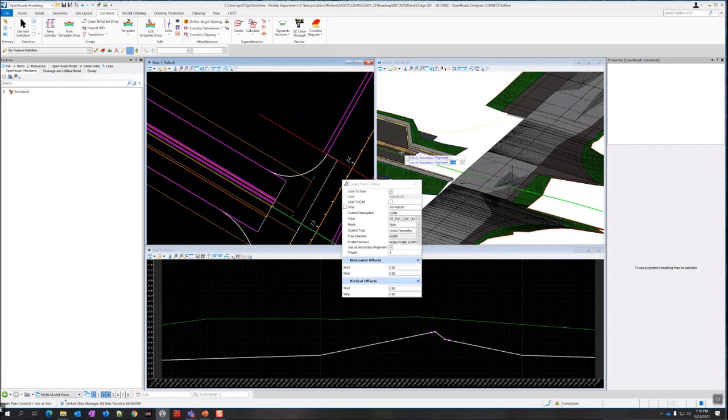If I just point control it without using a secondary alignment, it would just shift this over, and by the time you get over here, dimensions are all going to be wrong. So by saying use a secondary alignment, it's going to come to this radius, and then it's going to change the interval. Instead of going this direction, perpendicular to the center line, it's going to now be perpendicular to this radius. So that's the secondary alignment part.